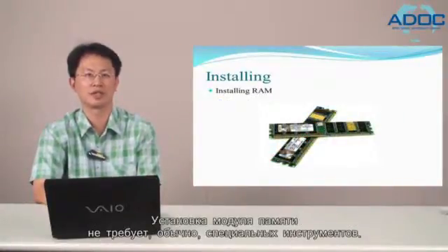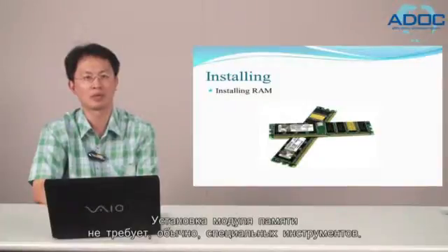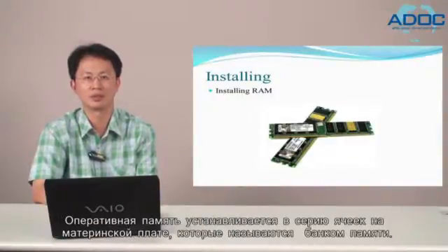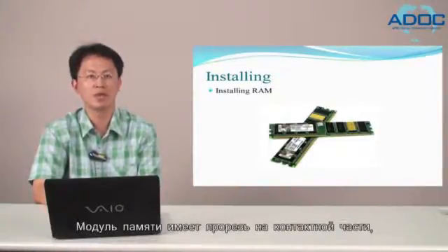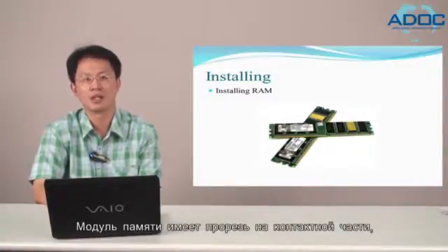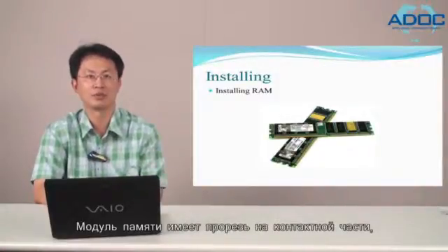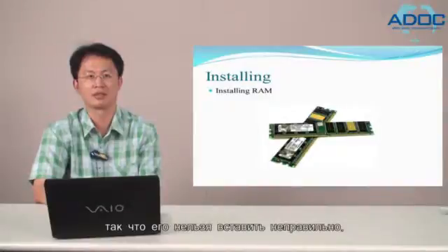The actual installation of the memory module does not normally require any tools. RAM is installed in a series of slots on the motherboard known as the memory bank. The memory module is notched at one end, so you won't be able to insert it in the wrong direction.